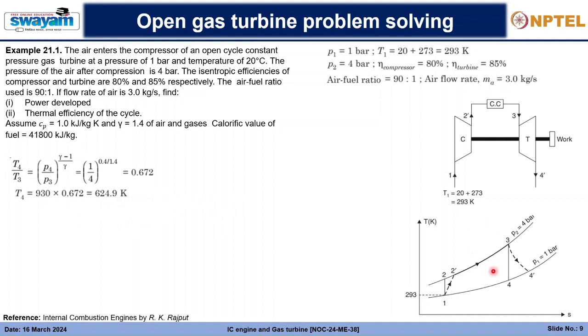So that's great. We got the value of T4, but that is not actually the temperature because there are certain efficiencies related to the turbine as well. And we will consider this efficiency now like this. So eta turbine equals (T3 minus T4 dash) divided by (T3 minus T4). So that is the actual work done divided by the isentropic work done. So always lesser by greater, right? This is lesser, this is greater. So that's how we will also see to this.